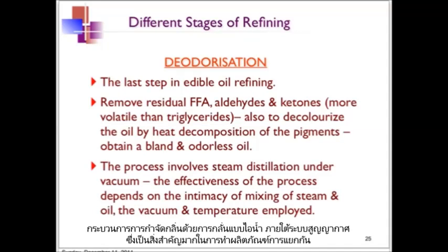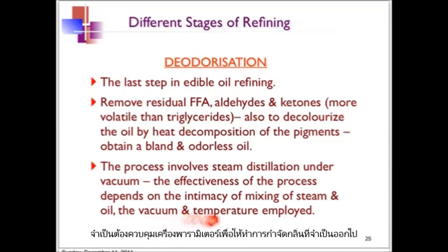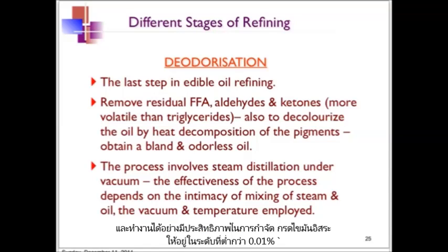The process of deodorization is basically a steam distillation done under vacuum. So it is very important during this process to get a very intimate mixing of the steam and the oil, as well as the right vacuum and temperature. The control of these parameters is important to get an efficient deodorization, to remove the free fatty acid down to a very low level, less than 0.01%.